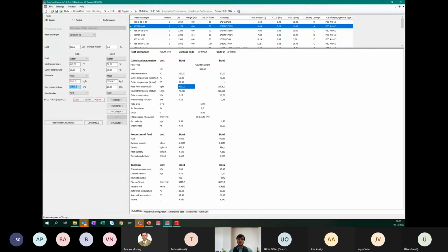Secondary side pressure drops are usually not an issue, because we have some pumping capacity with safety, or maybe it's even a new building where I can select a slightly higher pressure pump to maybe optimize the whole performance of my system. Why am I saying that? Because look what happens if I simply, instead of 20 kilopascal on the secondary side, put 25 kilopascal.